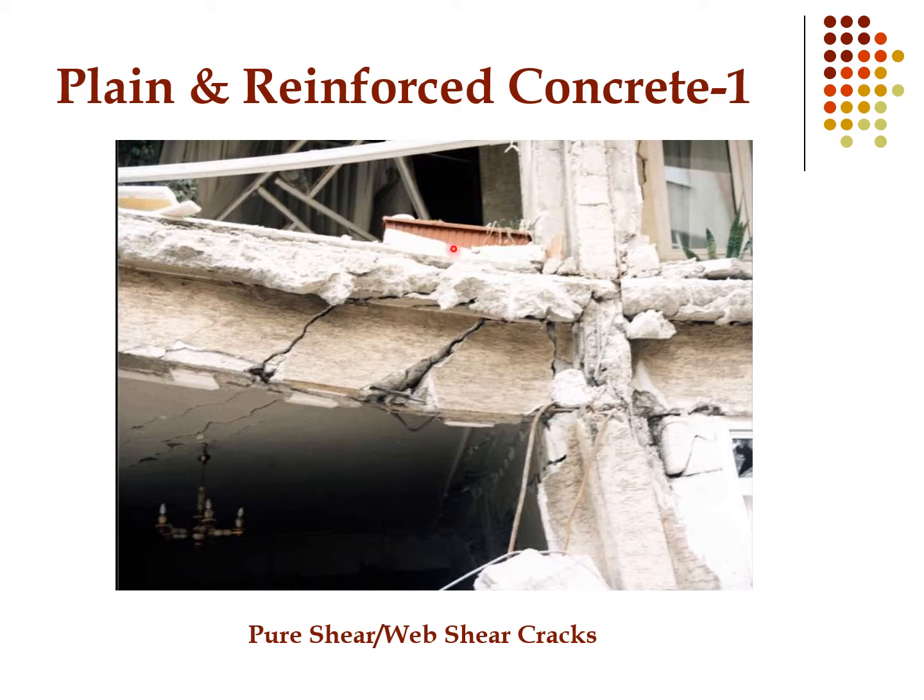This is an example of pure shear crack. You can see that these cracks are roughly at around 45 degrees. These inclined cracks are a pure, physical field example of shear crack.